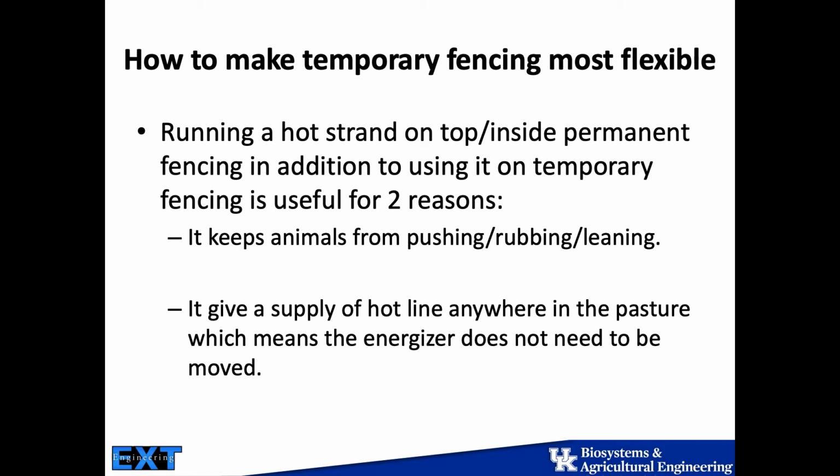And the fencing schools, for anyone else to talk about more permanent high tensile electric and where we do really want to connect them to make it seem shorter, to make the fence see itself as shorter, we'll discuss there. But if you have 5 strands, you want to connect all 5 strands at both ends, and that actually does shorten the length and make the fence look shorter. But connecting one strand in a full loop doesn't really do that.